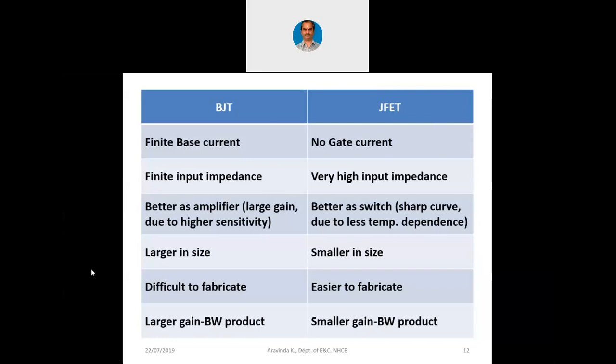But we are now in the era of VLSI, very large scale integration, where in fact in Chandigarh the foundry is also a VLSI foundry only, but it is 180 nanometer. But as such, now the device size of MOSFETs has come down to 90 nanometer, 45 nanometer, 22 nanometer and even 10 nanometer. Right now, Intel is working on MOSFETs having a channel length of 10 nanometer. Channel length simply means the gap between source and drain. That can be as small as 10 nanometer.